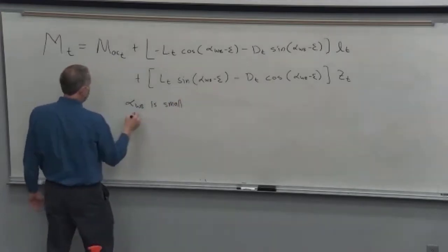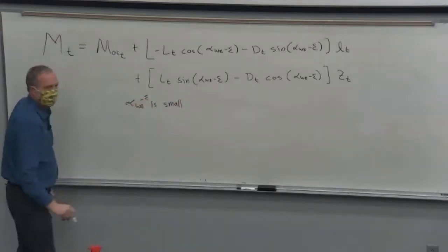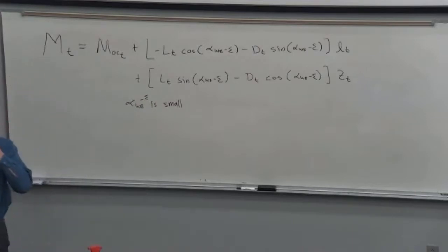And we have epsilon in here, so obviously if we subtract epsilon, we get even smaller. So if you end up working for a company and they're doing stall flight dynamics, you're going to say, well, you can't do that simplification, and you might impress your boss that you know that you can't because he knows it. But if you end up working for a fighter airplane company and they start doing high angle of attack maneuvers, like 45-degree angle of attack for some super maneuvers and stuff like that, then you have to include all these terms in there.